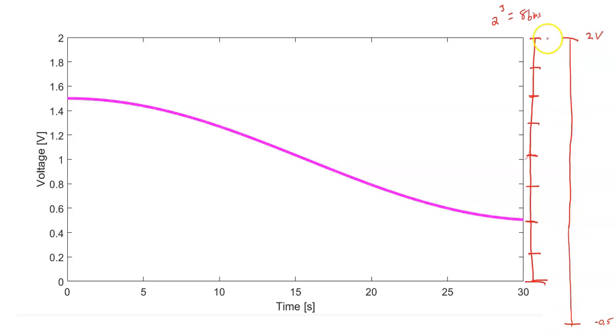And we can see that if we still had the 8 bins for a 3-bit converter, these bins would have to be much bigger, right? So it's important to recognize that our full-scale range and our number of bits work together to determine how much voltage difference there is between each bin.